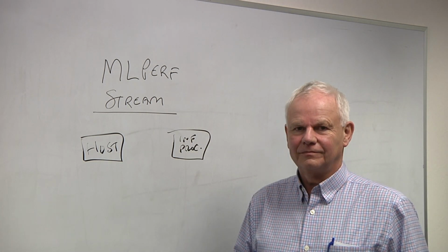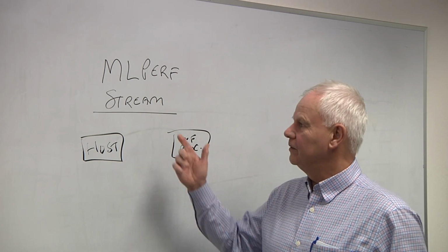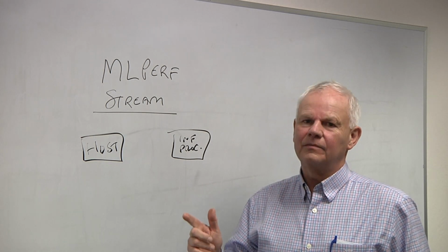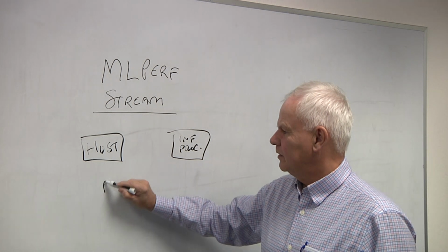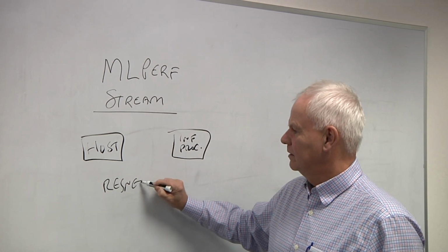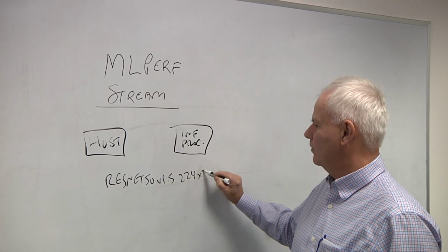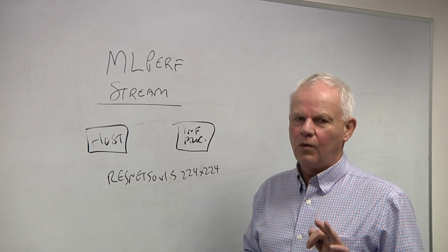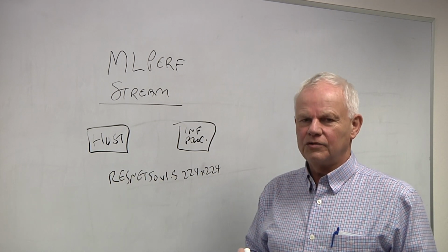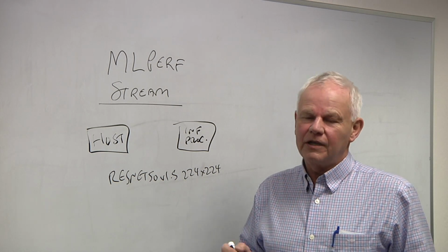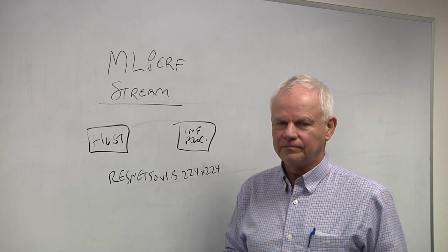So how exactly are those measured? Well, the way MLPerf has set this up is their benchmark is measuring the latency under the following conditions. So it's for a particular model, ResNet 50 version 1.5, 224 by 224. And something to note is that 4 out of the 5 of the benchmarks are for very small image sizes, which are generally unrealistic for edge applications. In the edge, you want to be at a megapixel. Only one of these 5 benchmarks is at a megapixel resolution.